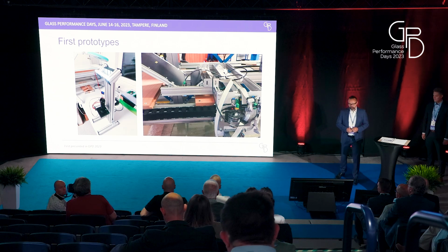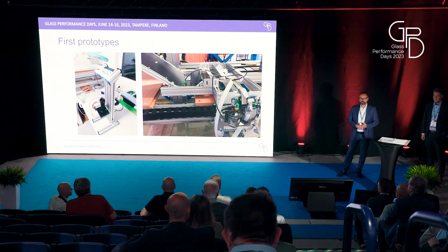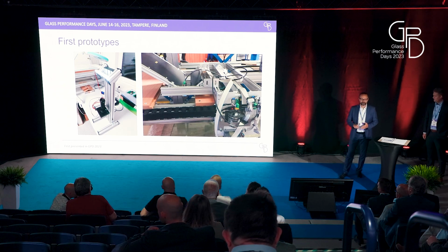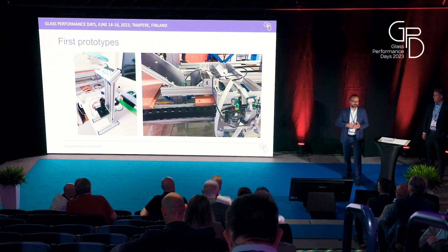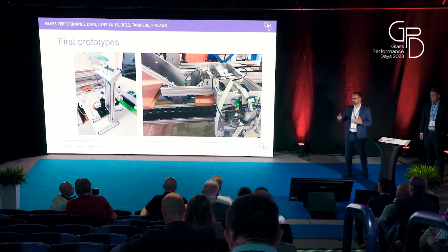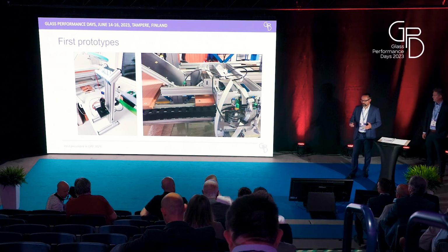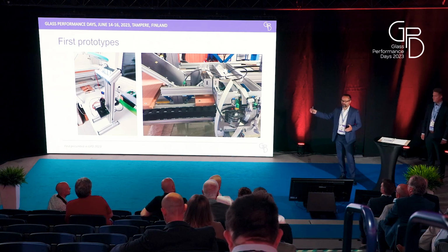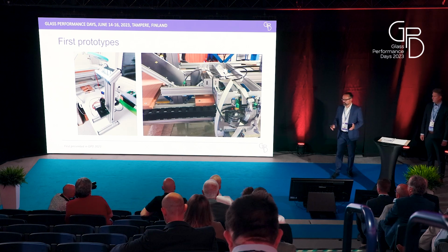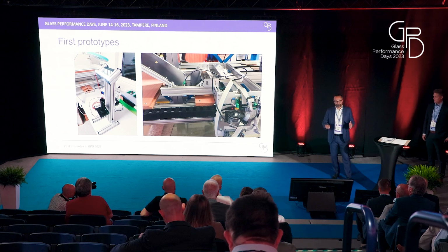So, you know, normally a vision inspection system in the flat glass industry works with a so-called light transmitted method. So that means that on one side of the glass you have a light source, on the other side of the glass you have an optical sensor, and if there is any kind of disturbance on the glass, it means that the emitted light will be absorbed, and this can be measured and visualized. So what we started with, we played around with a couple of different setups. As you see on the left-hand side, we played around with camera-based solutions, we played around with linear image sensors. We did play around with different light sources, ring lights, LED light, different wavelengths, and so on and so forth.